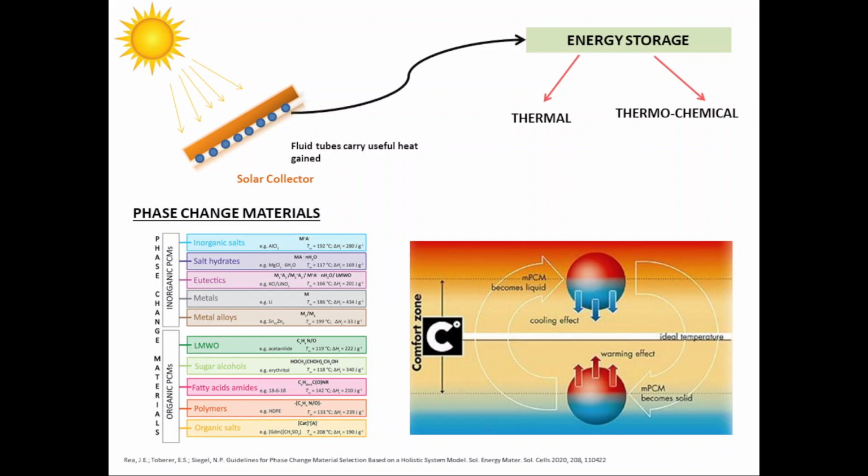So using these thermochemical energy storage systems for a short term purpose may not be good, because having a system which can store your products at such a high pressure of 100 bars will be expensive. That is one of the critical disadvantages of thermochemical systems.